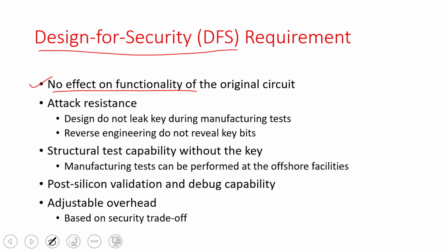That has to be ensured. And then attack resistance: reverse engineering cannot reveal the key bits, and the design does not leak the key during the manufacturing test, right. So you have to hide the keys from the attacker.